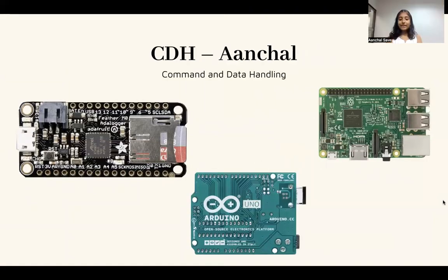For the command and data handling subsystem, I researched potential microcontrollers and I weighed the benefits and downfalls of the different options, ensuring that they fit the requirements we stated earlier. I ended up deciding on the Adafruit Feather M0 Adalogger because of its ability to store data on a microSD card without an outside extension, as well as its capability to use I2C wiring, among others.